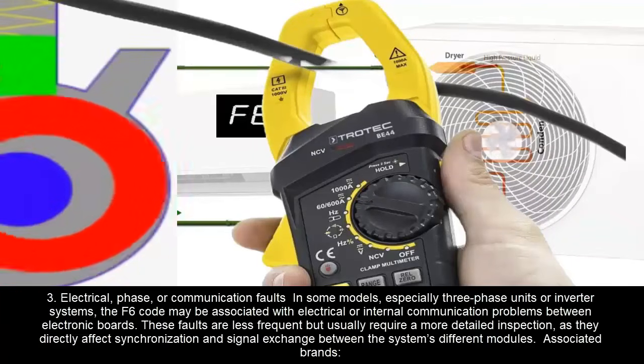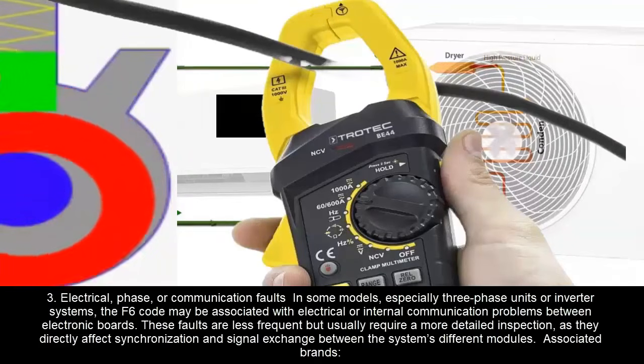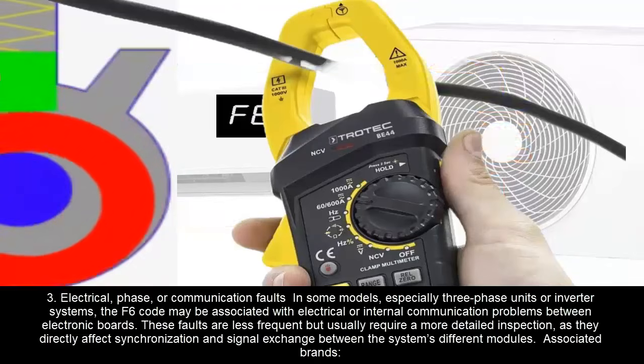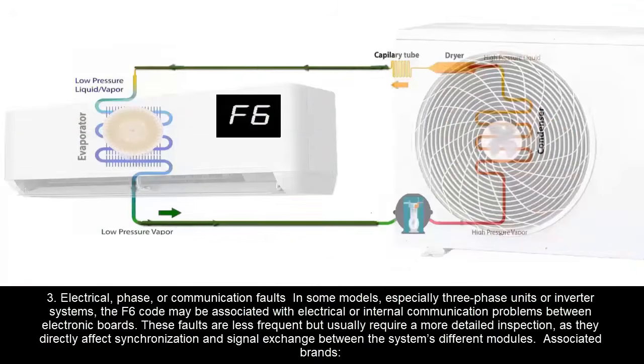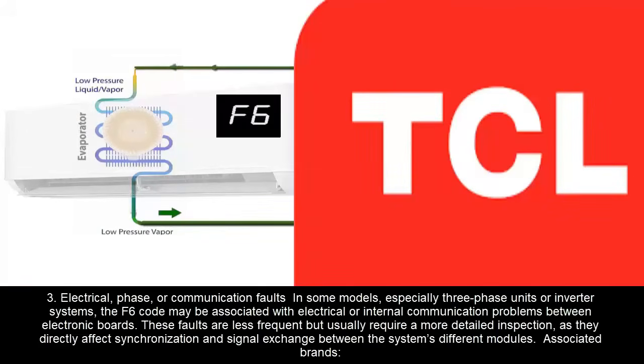In some models, especially three-phase units or inverter systems, the F6 code may be associated with electrical or internal communication problems between electronic boards. These faults are less frequent but usually require a more detailed inspection as they directly affect synchronization and signal exchange between the system's different modules.